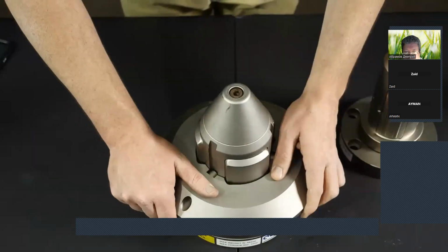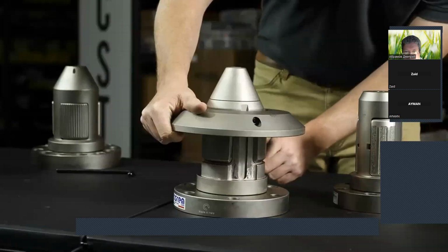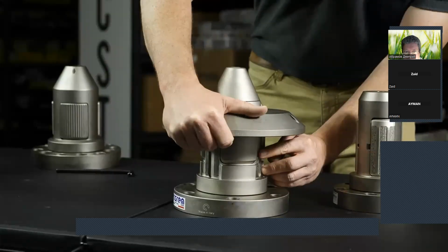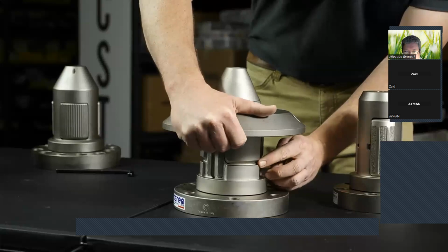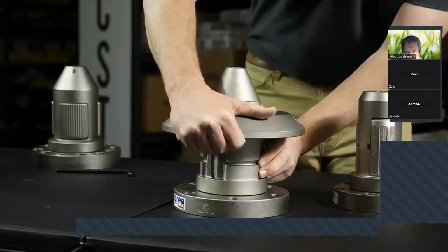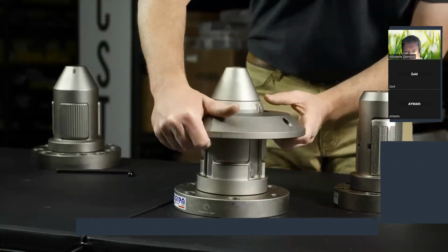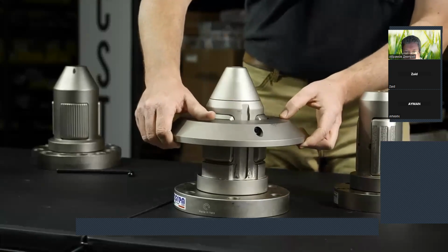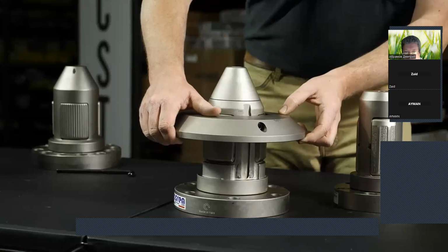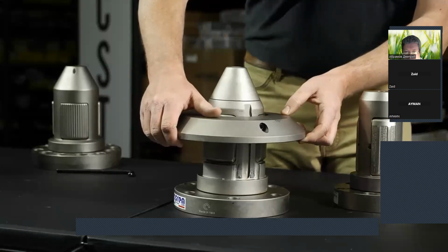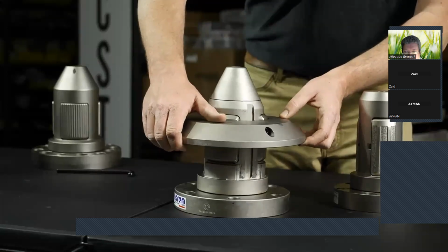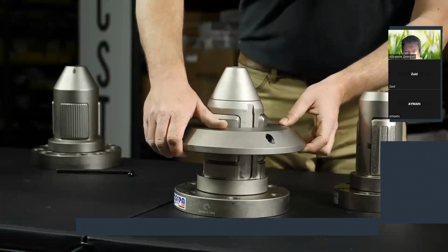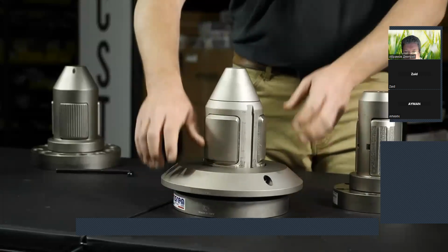Another waste-reducing feature of this chuck is the cutout runout ring here at the bottom. This is designed to keep operators from accidentally chucking up too far. It makes sure that the chuck makes contact with the core and not the roll or the paper. If you have manual roll loading, this helps stop operators from using too much side pressure and chucking up past the core and into the paper itself, reducing paper waste and helping plants achieve their goals of running the roll all the way down to the core.